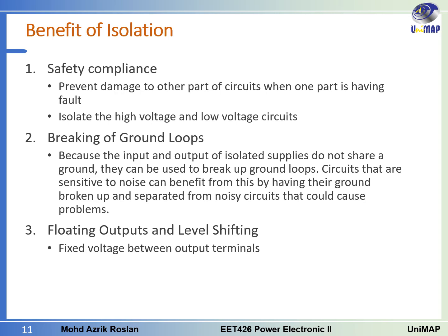What we mean by floating output is that because you disconnect the ground from the input side to the output side, you can have a fixed voltage between the output terminals, but this voltage at the output terminal is not relative to the voltage at the input terminal.